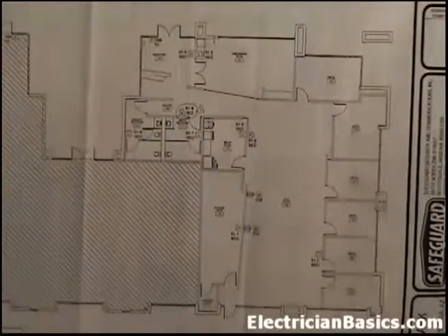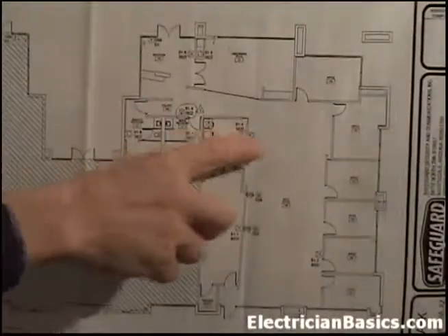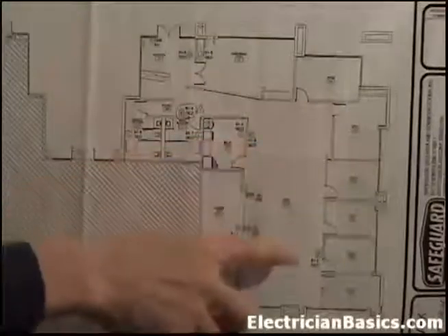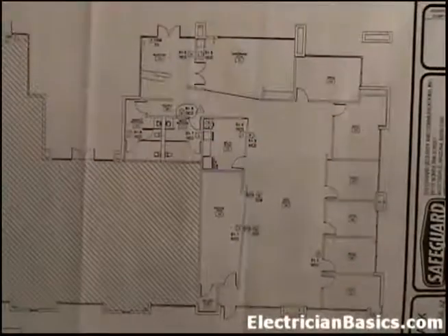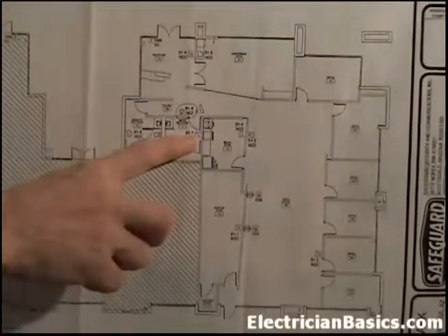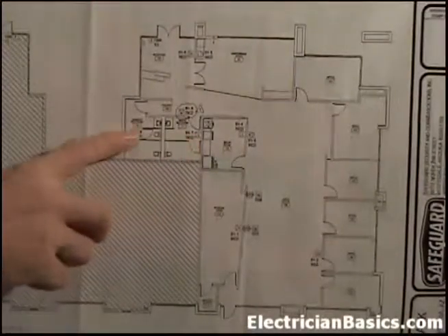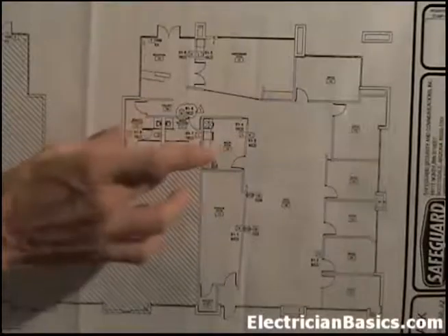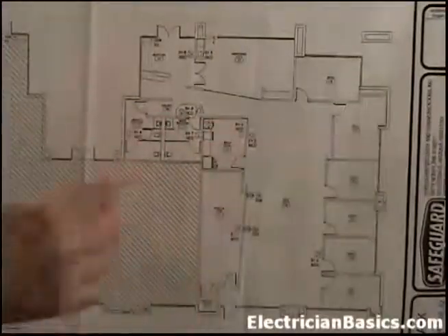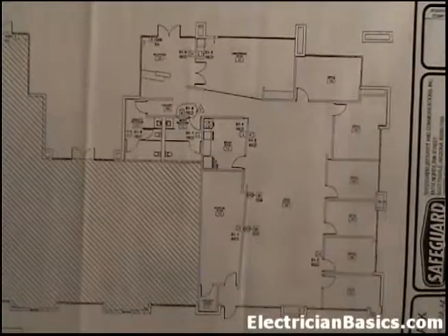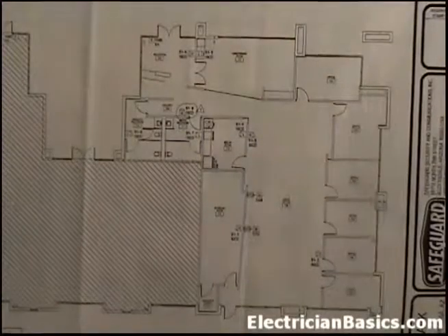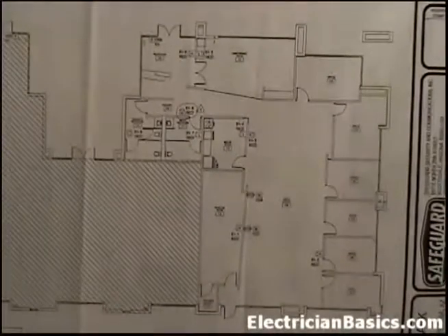You can't come in and say, oh well, this is going to be 3 and 4, what difference does it make? Well, they're in different rooms. 4 is in the break room and 3 is out here in the open office area. You can see this is 7, it's in the men's room, so you can't switch it with 7 and 8. Even though they're close to each other, you have to keep them in a certain order because they're addressable. It's like your mail has to get delivered to your address, not your neighbor's address. So that's what addressable means, that specific location.